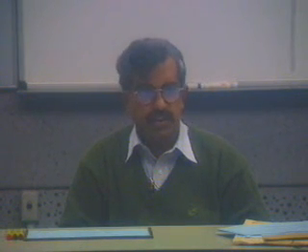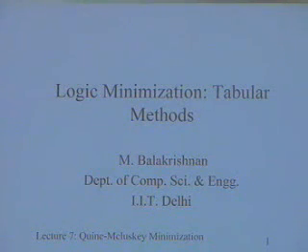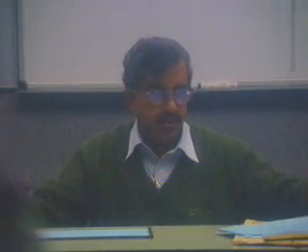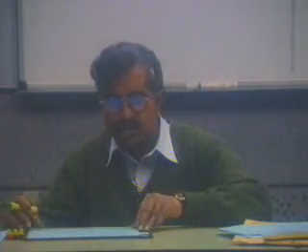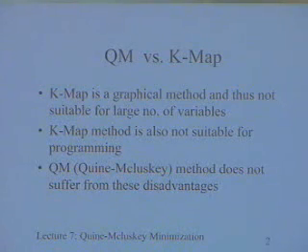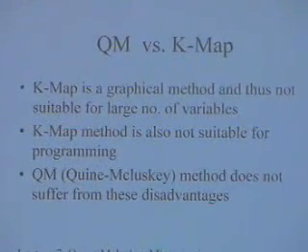Okay, so today we are going to talk about the problem of logic minimization. Previously we had discussed the Karnaugh map method for logic minimization. Today we will talk of an alternative method, which is called the Quine-McCluskey method. There are a number of other logic minimization techniques that have evolved, but primarily they all revolve around a similar approach as Quine-McCluskey, and there is an evolution from that.